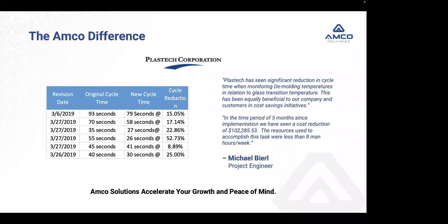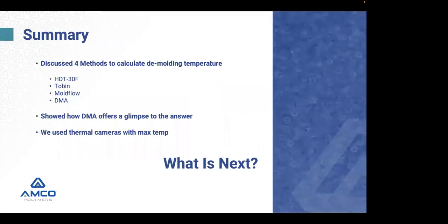How many times has an OEM or someone come to you and say, well, the customer down the street says they can run a faster cycle? Well, guess what? If you're doing scientific molding, systematic molding, you're filling as fast as possible, gate freeze, I've optimized my cooling time, plastification time. There's really nothing you can do to be any faster.